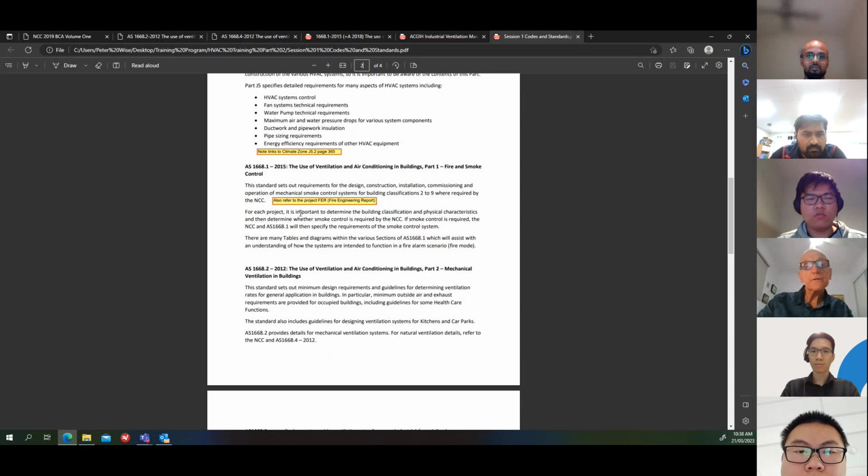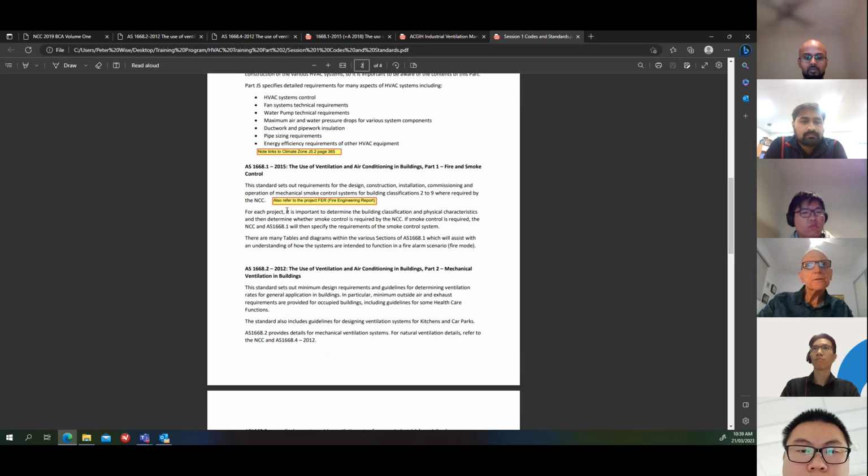So if the fire engineer or the FER says you need to do something, then you need to do it. It doesn't say you can't talk to them and try to change the FER if you want to. If the fire engineer agrees with your argument, then he or she can change the FER, but you'd have to have a convincing argument. But it's been done. I've been involved in those processes, and if you've got a logical argument for why you don't need to do what they've asked for, it's worth trying.